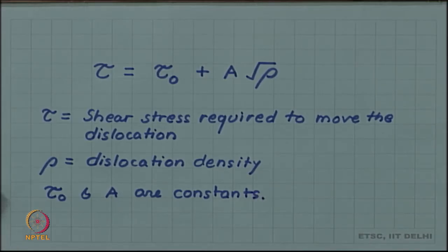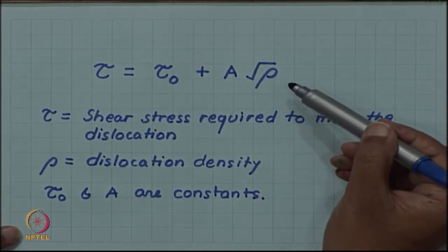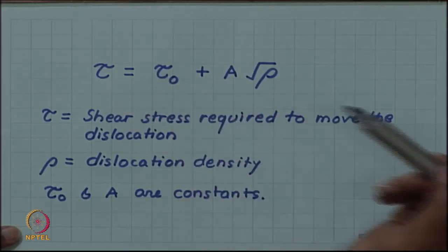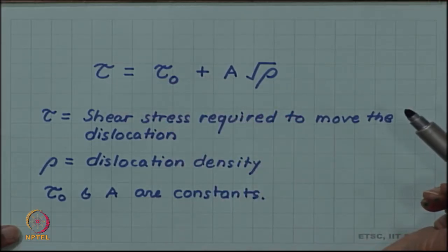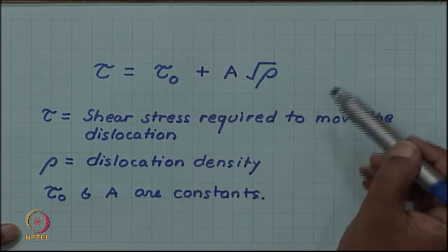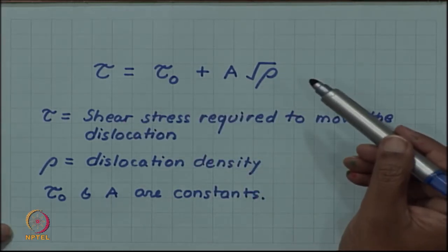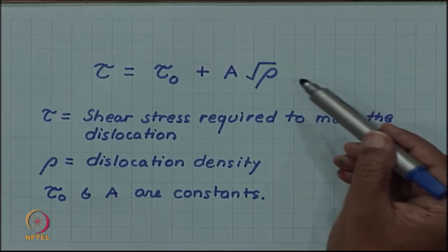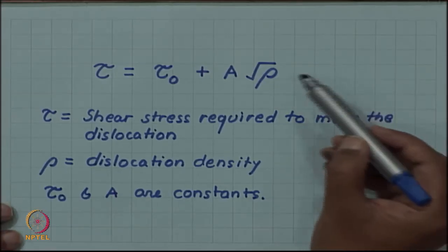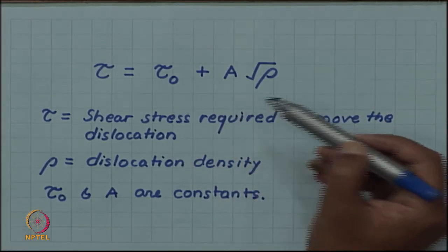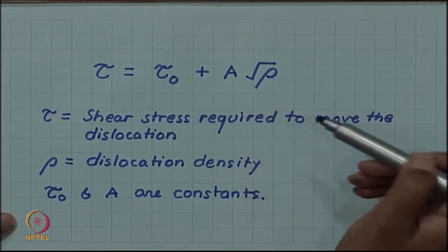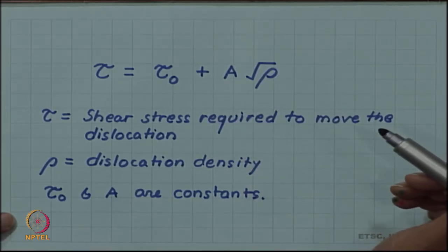So, you can see as the dislocation density increases, the stress required to move the dislocation will also increase. We are not deriving this relationship, a simple derivation sometimes is possible in terms of a simple model of dislocations, but we will not go into that, and empirically also sometimes such a correlation can be established.